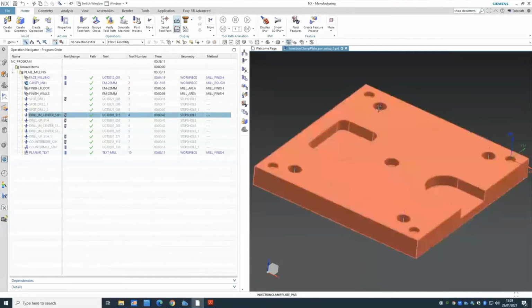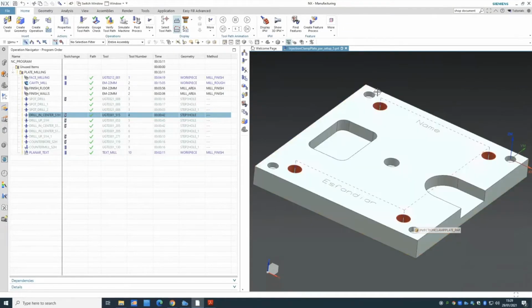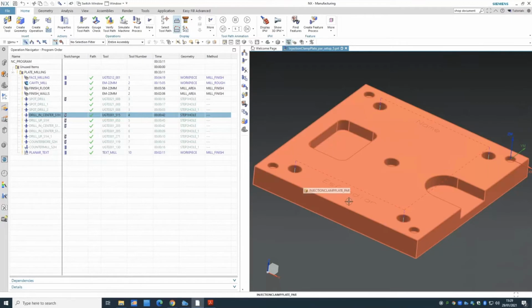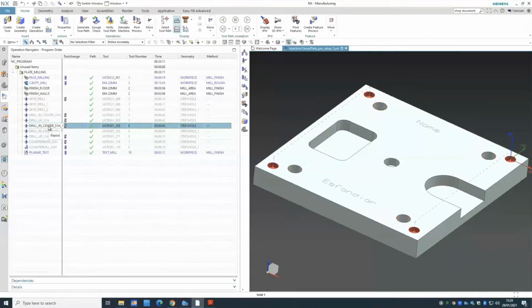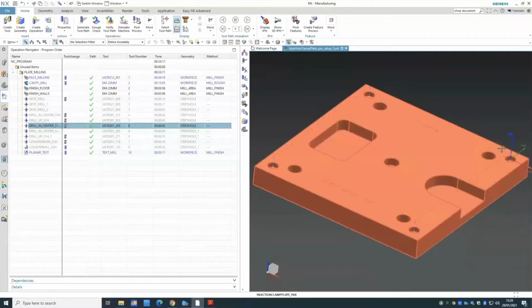Technically, if I go from here to here, and then do that kind of zig move, because it's at 45 degrees, I can do the G00, the rapid move. It goes as fast as possible because it's at 45 degrees. So it goes there, then makes a cut there, and then makes a cut. So it can do that. But usually the change is marginal. Once you have more holes on the sides, then doing those kinds of things is important. Why shouldn't you do that? Especially in your assignment, you have several holes.